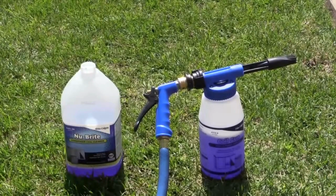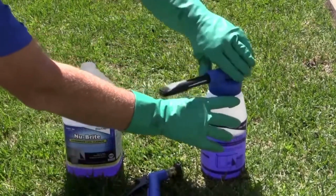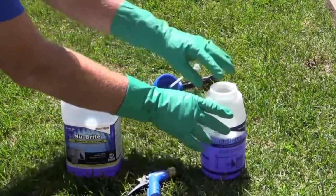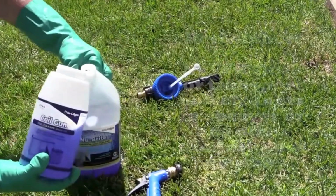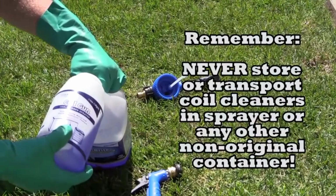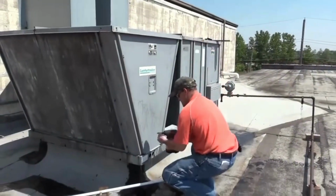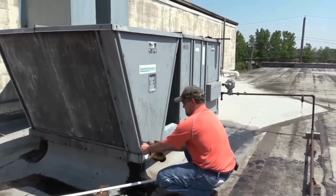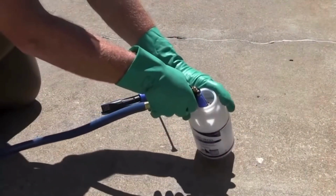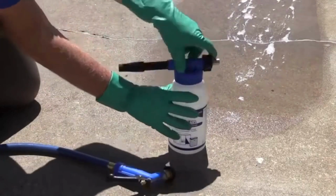When the coil has been adequately rinsed, return any New Bright to its original container and rinse out the coil gun. Remember, never store or transport coil cleaner in the sprayer or any other non-original container. Complete the setup of any other materials, reassemble any panels removed for cleaning, and return power to the unit. Make sure the coil gun and its accessories are thoroughly rinsed with water after use for maximum service life.